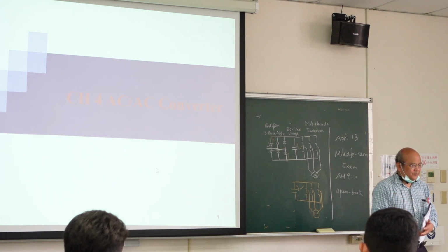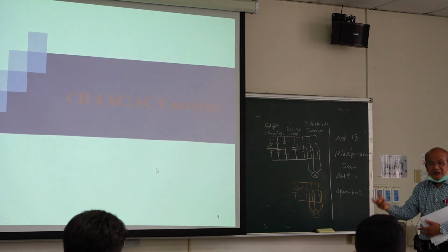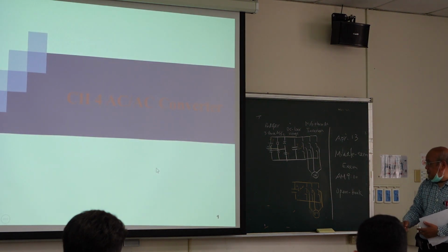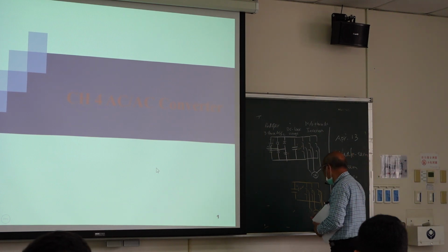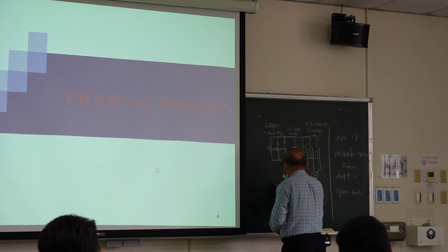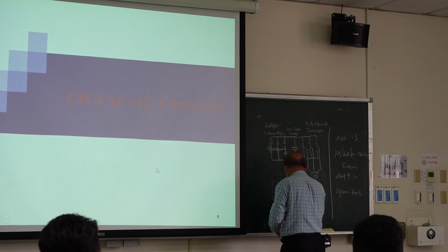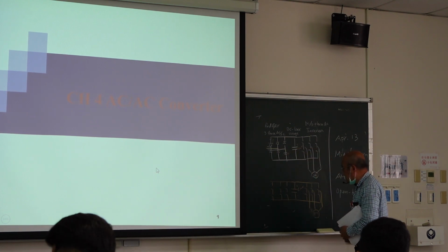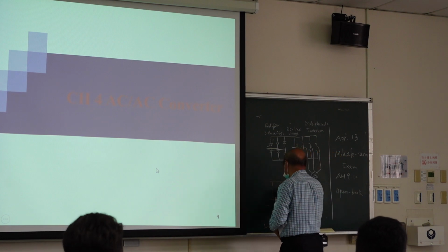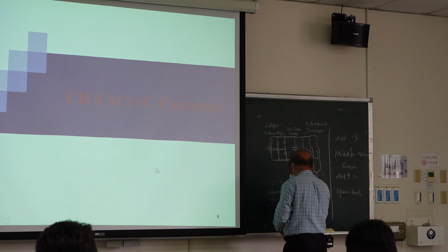So if you need power factor correction, what do you need? You need to control the AC current. If you need to control the AC current, then you have to redesign the input side. So you have to use IGBT to control it. So you have input voltage here.